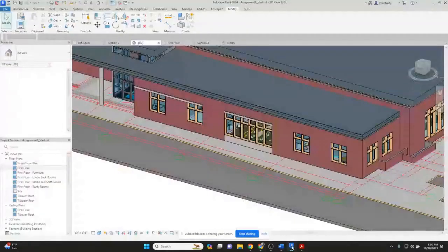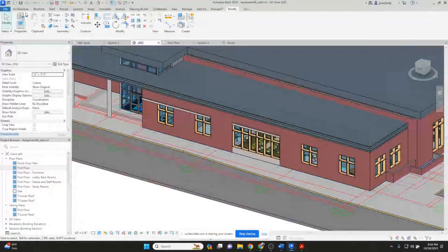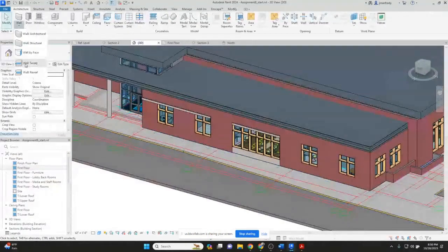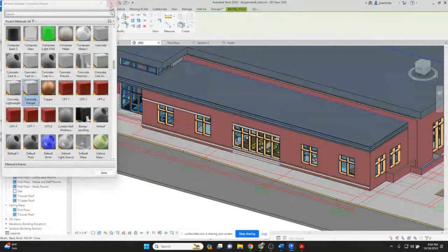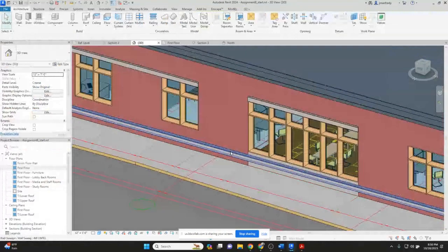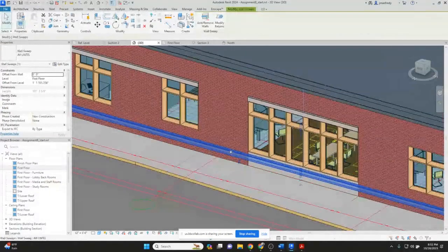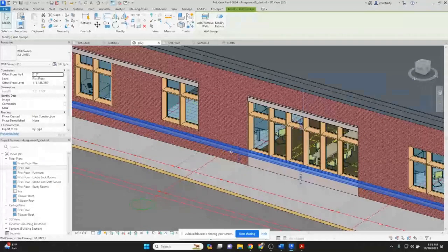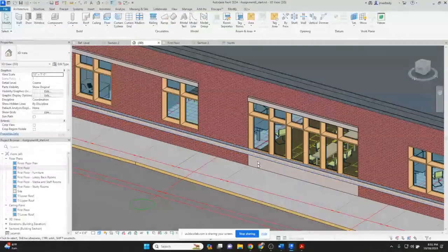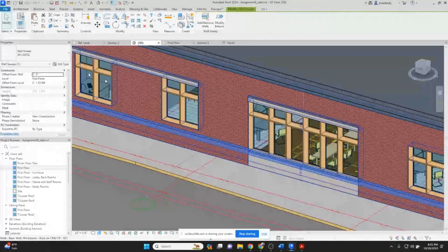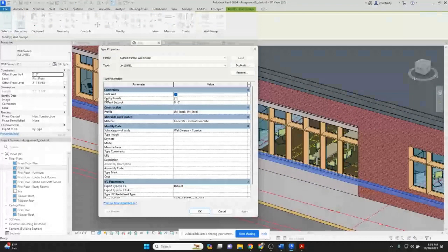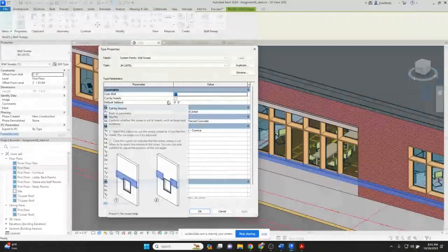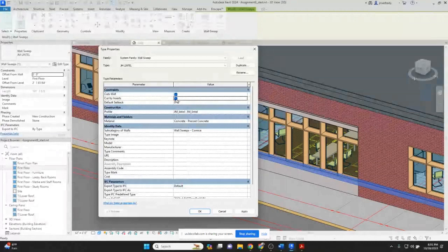If I take my current sweep, just to show you, and add it to the entire wall, hit enter, you see it actually skips over. If it ran into a window in the wall, you see here, it goes on top of that window. And I believe there's a tool in here that lets me, you see cut by inserts? If I choose that option, it should cut out the lintel when it reaches a wall opening, like a window or door.